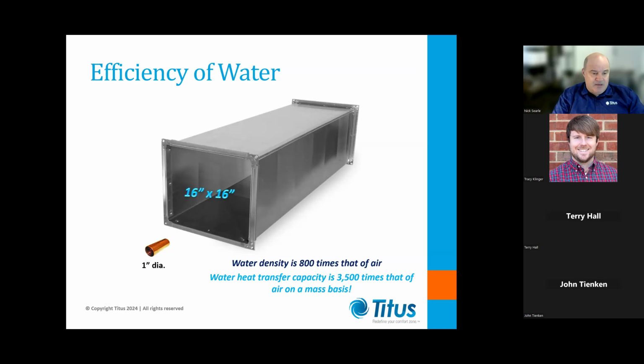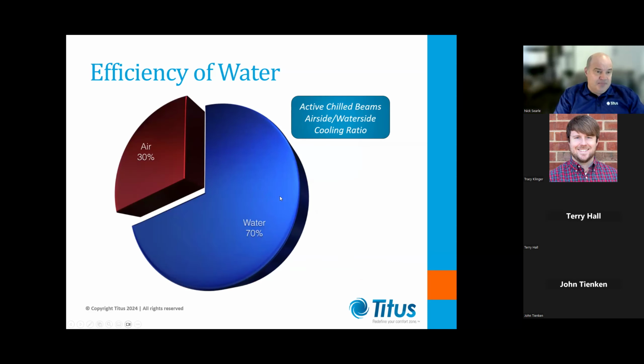One of the things you notice about a chill beam installation is if you put your head up into the ceiling void and have a look around, you see much smaller pipes versus a lot of sheet steel ductwork that you would get with the conventional VAV system. So far more compact. Now, we still need air to accomplish the dehumidification and ventilation from the central air handlers.